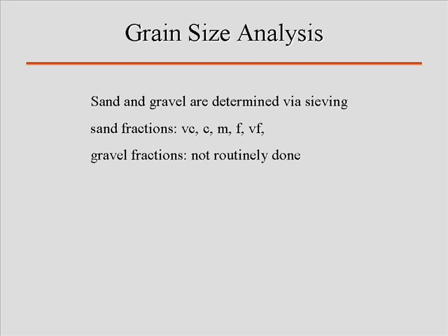They're not cheap, by the way, so go easy with them. You also have to have some sort of means to draw the fluid through as quickly as possible. Vacuum filtration is the way to go. But the real issue is you've got to have those filter papers, and they've got to be pre-weighed, because you've got to weigh them before in order to determine how much the weight is after.